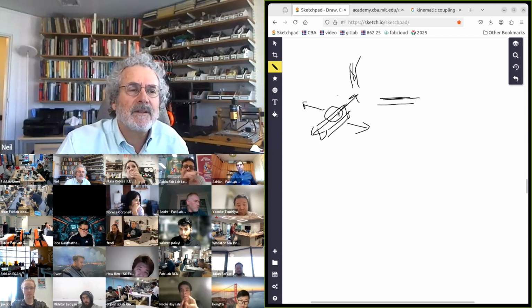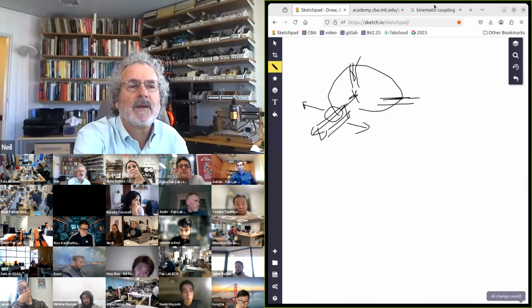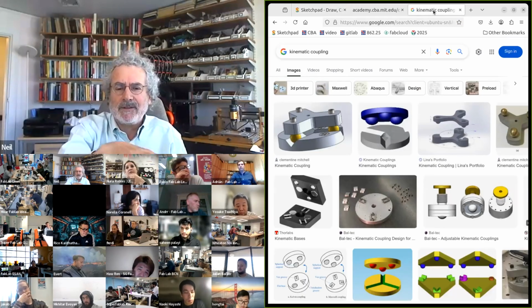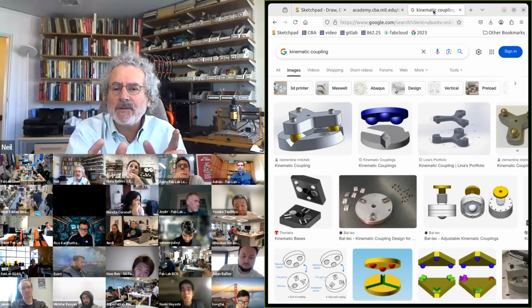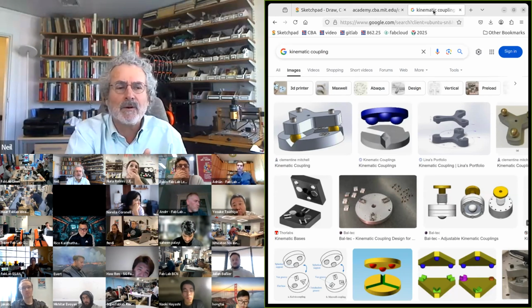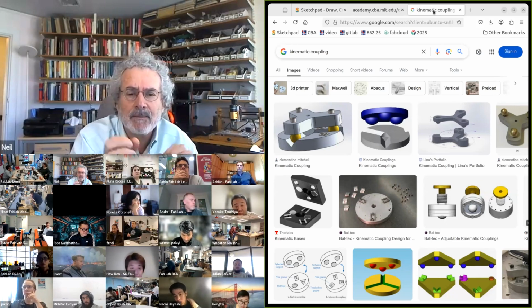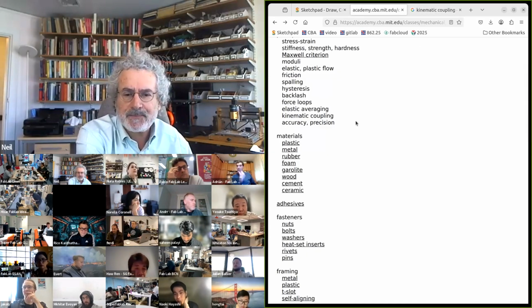And so it means the total structure can only go in one position. So if you just slap this down, it seems like coarse positioning, but there's only one solution for where each ball goes that registers it. And so it lets you take two parts and align them to very tight tolerances.